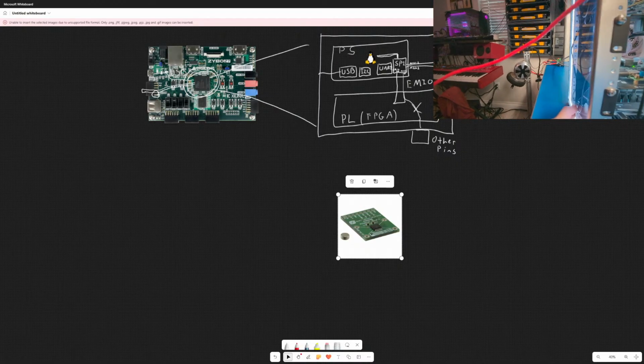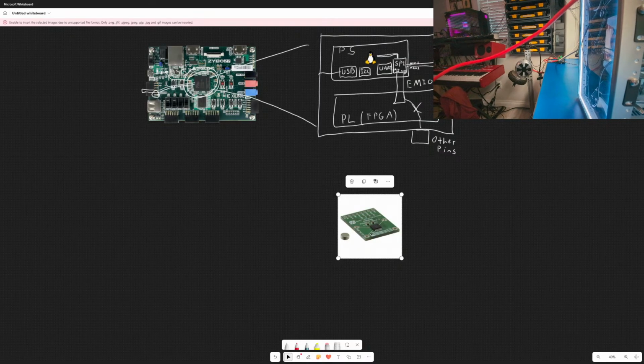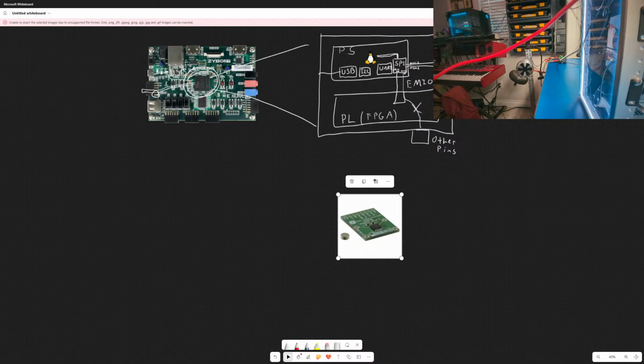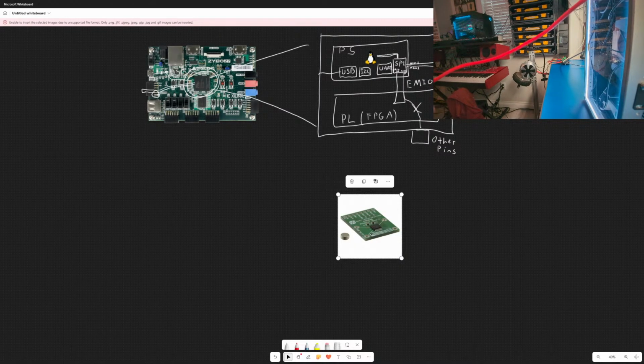It's kind of hard to see, but there's a little motor controller over there that's an ODrive. It can control two hoverboard motors at once. The problem that I found out very early on was that there are encoders built into these. They're called Hall effect sensors, and it's actually pretty clever. You're essentially measuring the pulses.